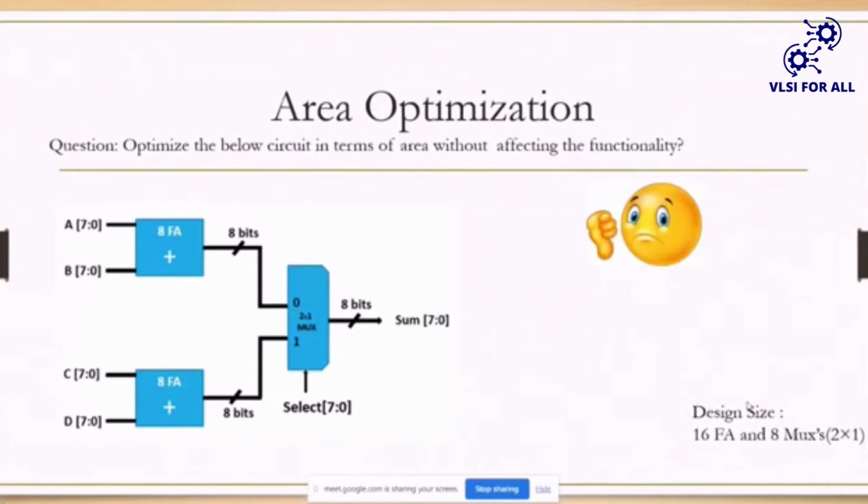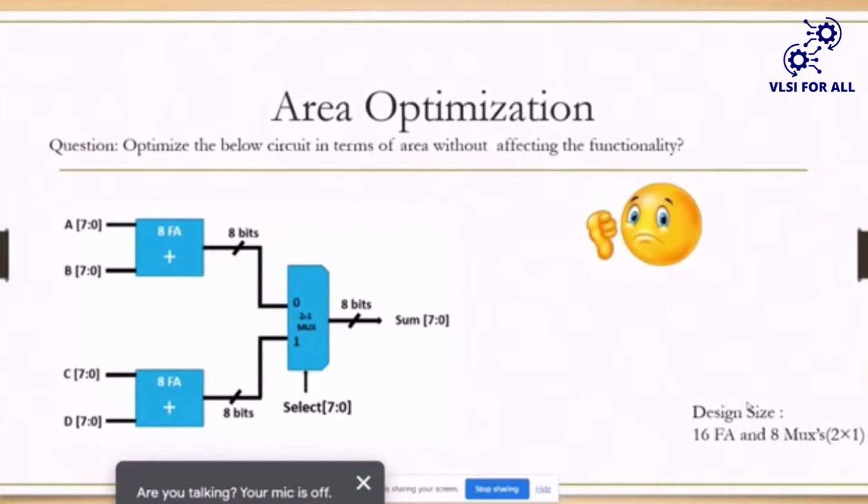So if XOR gate is present in a particular design, the power dissipation is more for that design. Hence we conclude, as XOR gates are present in the adders, adders are the power hungry devices. In your design, if possible, try to maintain less number of adders. That is the bottom line.